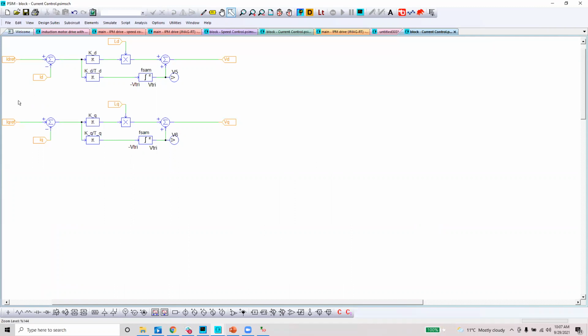That is something our own algorithm is working on, it's a very complex algorithm. When you have a saturation effect, your LD, LQ change with the current, then it's quite complex to do the maths there. But you can easily get these PI values to use for your hardware, your microcontroller, or whatever.